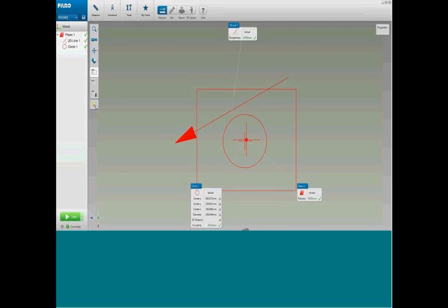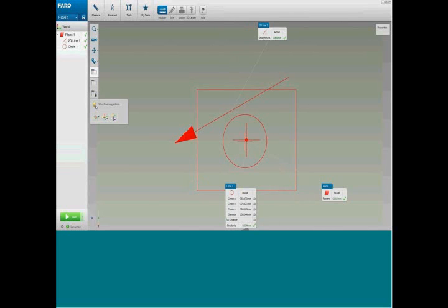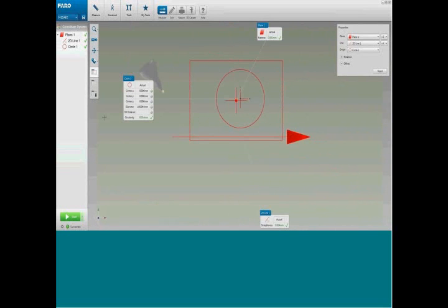If we click this, we now get suggestions from the software for the next step. So as I want to create a coordinate system, I simply hover over the icon to choose the one I want. In this case, plane line circle, and it's as easy as click, and your coordinate system is created, and your view is now aligned 2D to that coordinate system.